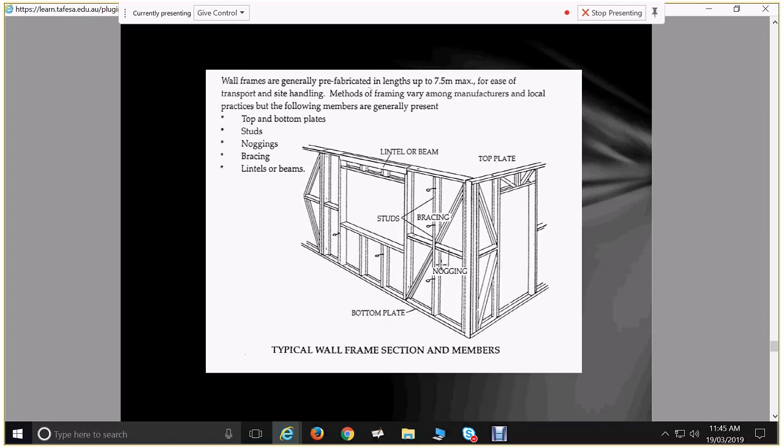Beyond that, other differences between your steel and timber frames, the way that you run pipes in there. Your steel frames, if you look at them, a lot of them have got these holes in the centre of their studs. So when they manufacture that stud material in the factory, it's manufactured with holes in it. And those holes line up, so you can just run pipe work through the middle of those frames. Whereas when you've got a timber frame, your plumber has to come along with a drill and drill lots of holes. When it's a steel frame like that, the whole process is controlled.